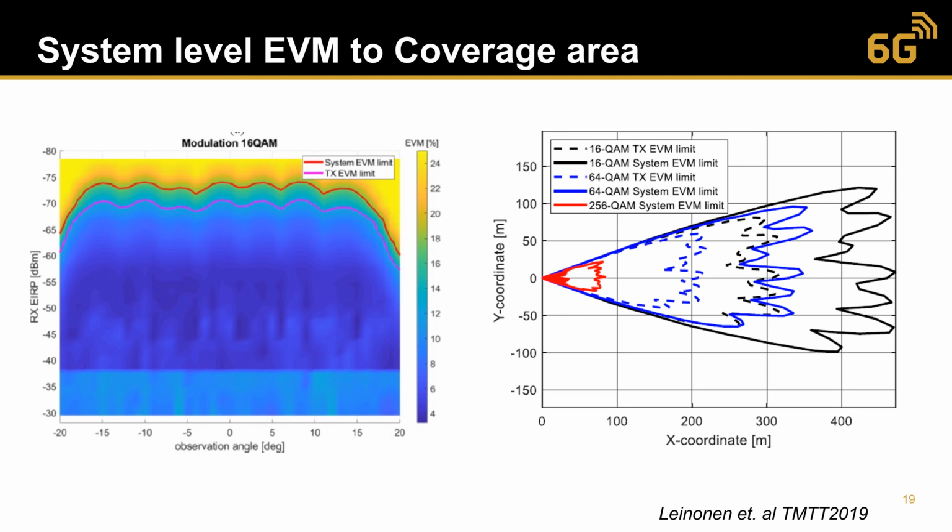If the radio signal is steered over beam steering angles, the full coverage of the cell can be constructed. Both figures present the same results but in different format. The figure on the left shows the signal quality over the signal levels, while the figure on the right converts the signal levels to coverage distance. It can be seen from the coverage figure that fine-grained beam steering is needed so that constant cell coverage and range is achieved.